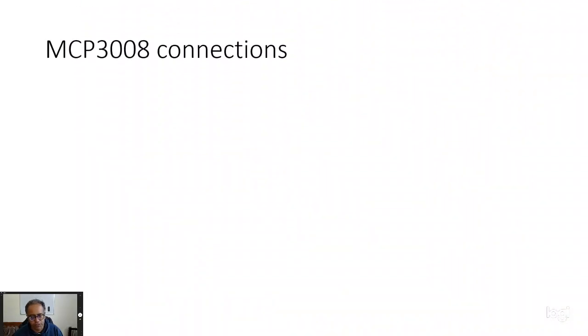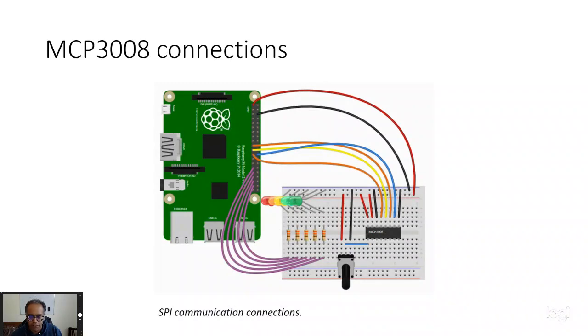Now what we are going to do is connect the instrumentation amplifier output to the ADC. And for this we will utilize the connections provided in the GPIO read the docs online document, right? So if you remember, in the first class I was saying that if you understand how this very basic configuration works, that you have a potentiometer, that potentiometer is now connected to the MCP3008. So you are converting a real world analog signal to a digital signal using the MCP3008. And that is exactly what we are going to do here, right?